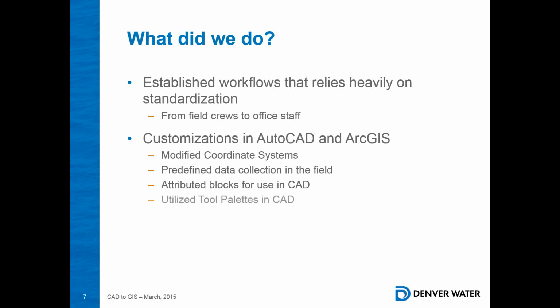Yep. Then we utilize tool palettes in CAD. So when you're out in the field, you only collect certain data. You're not going to be able to get everything. Those GPS collectors can't go under trees or bridges or something like that, and signals get blocked. So we have to add stuff back into our drawings for asset recording to post. Sometimes valves have to be added by the drafter rather than somebody out in the field. So we've created a tool palette.